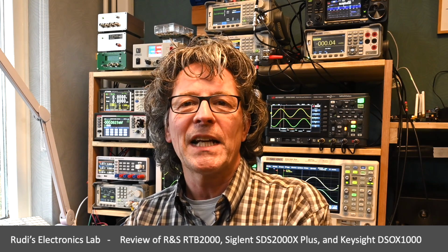If you look at the cursors, all the devices are kind of similar. They're all powerful. If you look at measurements, Siglent really has a number of things that the others do not have. Most in particular that we can exactly see which part of the waveform it's analyzing for particular measurement functions, the link that it has to the cursor system, and also that it gives us the histogram, which is very useful. You ask any statistician, if you really want to understand your data, you don't want only the descriptive statistics, but you really want some graphic representation of the waveform, so you really get more insight into the distribution here.